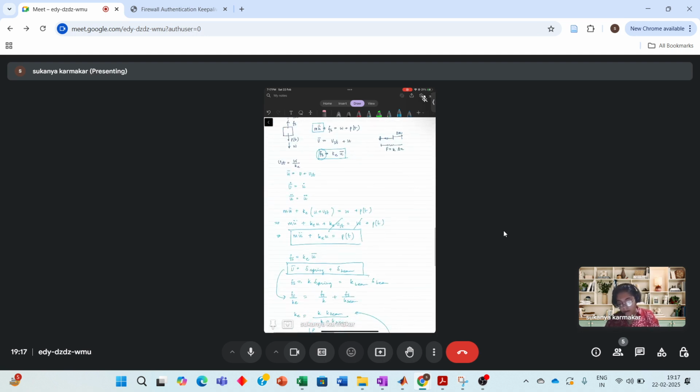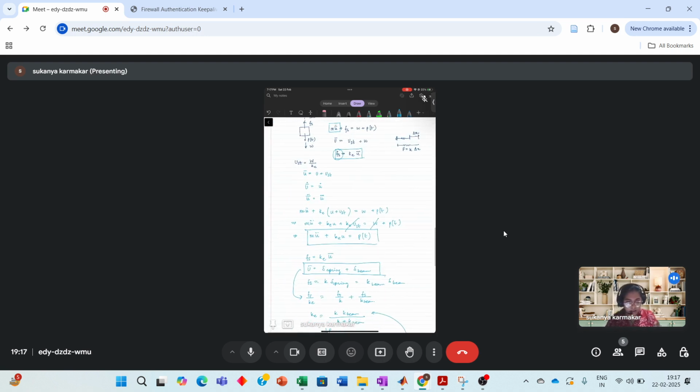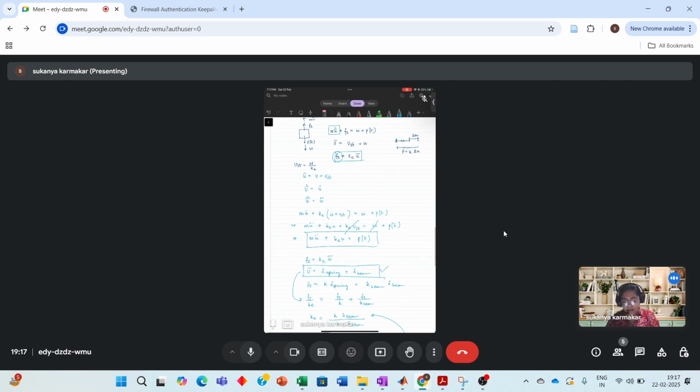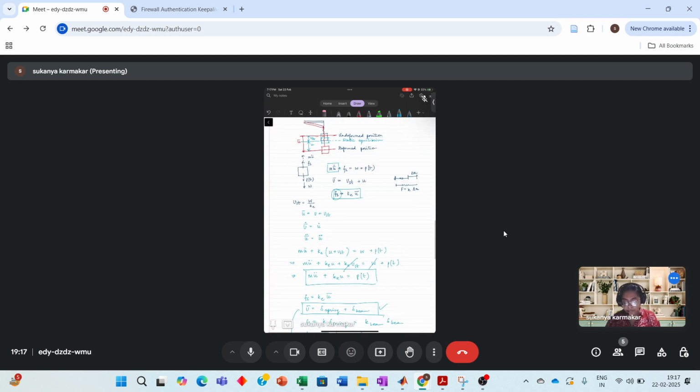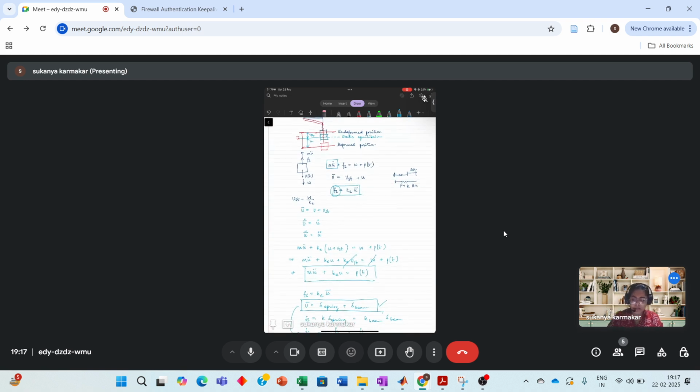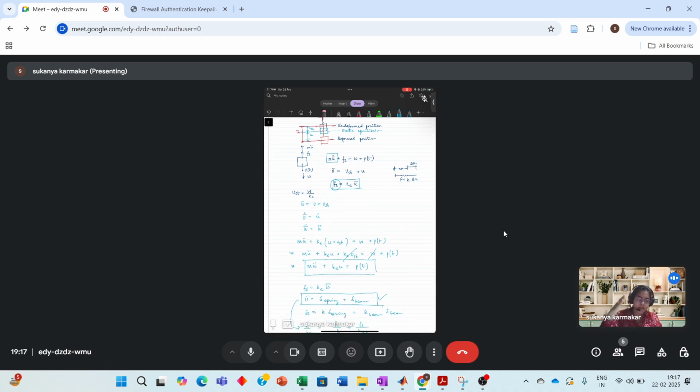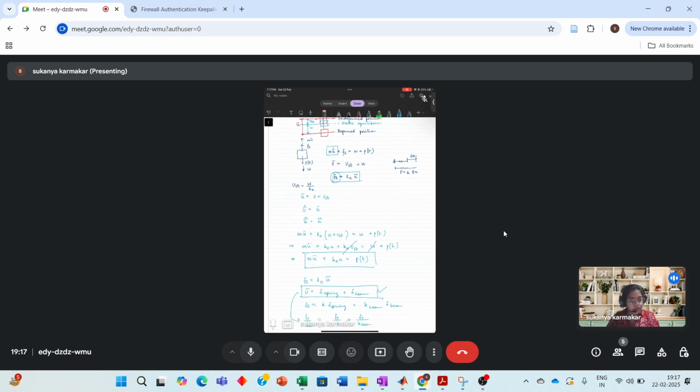Yeah, you can think of it in that manner also, but first think like this. What is the total deflection? U bar, what is total? You will have certain deflection which is happening because of the spring, because the spring is deforming, and because the beam is deforming in the transverse direction. So is this equation clear for U bar? Yes, ma'am. U bar is clear.